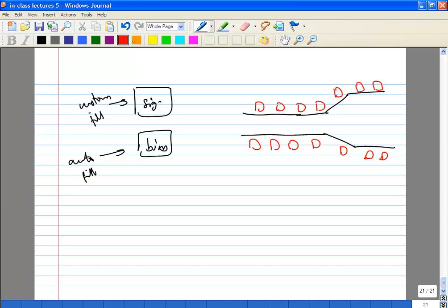And typically what you'll have to do is, around inductors, you can leave out fill. Okay, normally around the inductors, the foundry will give you some waiver, because obviously the inductor is going to be huge. It may be 200 microns by 200 microns, and that means that area is definitely going to have low density for lower metals. Okay, and you can't do anything about that. Usually the foundry will give you something called a waiver. They'll review the layout and they'll give you a waiver.